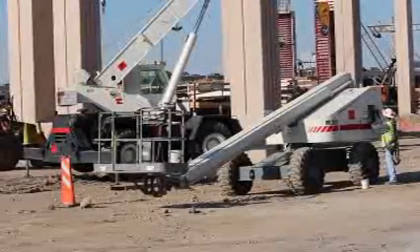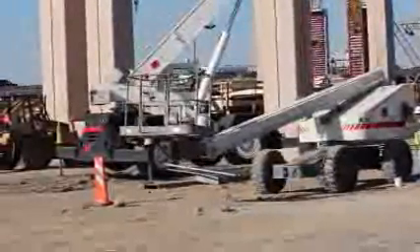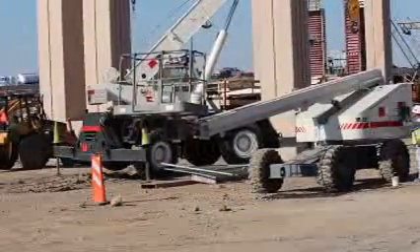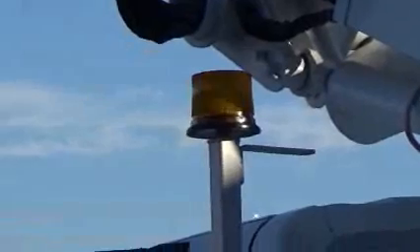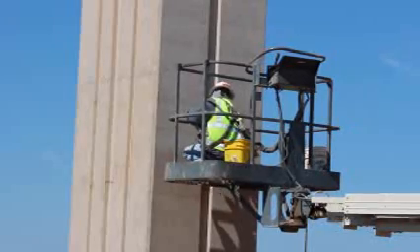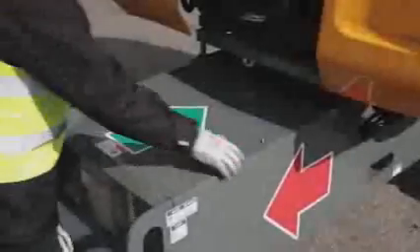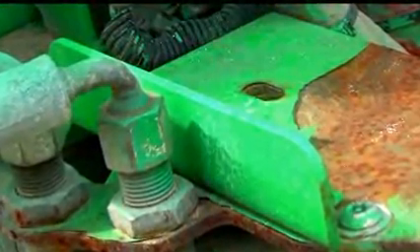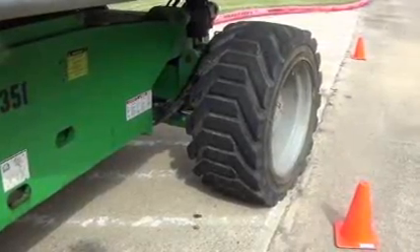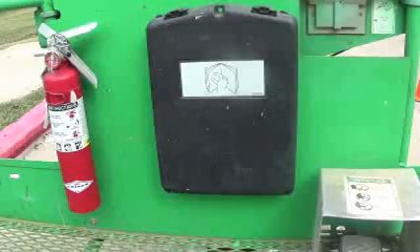A pre-start inspection must be performed every day or at the beginning of each shift by the operator, which includes, but is not limited to, the following: operating and emergency controls, audible and visual alarms, PPE worn while operating or occupying the MEWP, leaks to the air, hydraulic, and fuel systems, electric cables and wiring harness, loose, damaged, worn, or missing parts, tires, wheels, and wheel fasteners, instructions, warnings, control markings, and operator's manual,